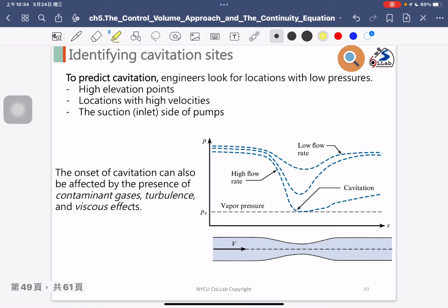So there are also some advantages if we can apply the cavitation problem. But cavitation knowledge for engineering is not good. So in practice, we should predict where we will have the cavitation problem. The major idea is that high velocity will result in low pressure, and when the lower pressure is less than the vapor pressure, you will have some cavitation problem.